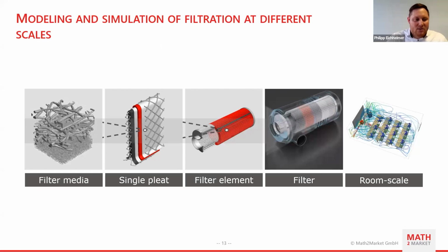But the real challenge is to take the findings we get on the filter media and import them to single pleats or filter elements, which is also possible in the software when we import, for example, CAD data, where we have complete filter elements also with housing. And from the very recent pandemic situation, we are also capable of doing room scale simulations where we use, for example, an air purifier and can run systematic studies on optimization, where you put the air purifier for the maximum performance, or reduce the operational costs when you optimize the air cleaning rate.